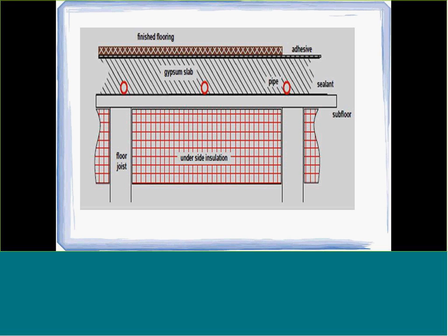It's self-leveling, and then you can put your finished floor over top of the gypsum. One thing you have to remember when you're doing this kind of overpour is you want to have at least 3/4 of an inch of overpour above the top of the tubing. So if you're using 1/2-inch tubing, the OD of the tubing is 5/8 plus 3/4 overpour. You're looking at a minimum of 1 1/4 inch overpour if you're doing a gypsum slab, and then you would insulate underneath of that slab.